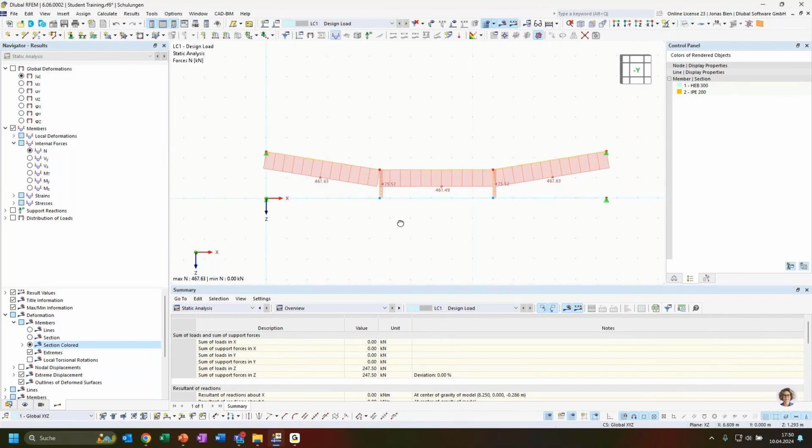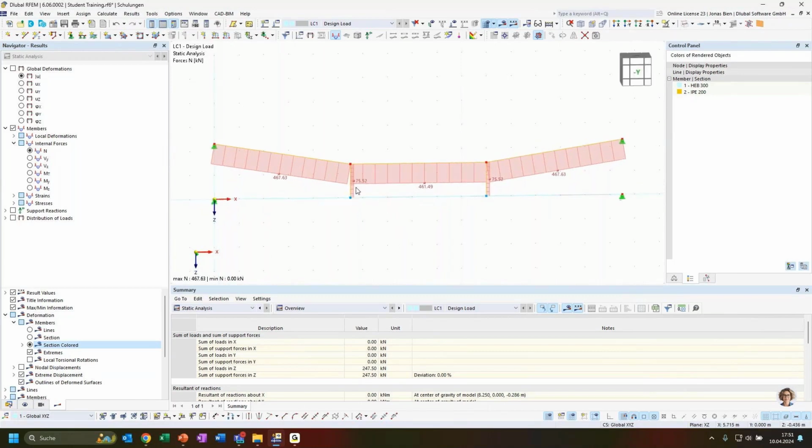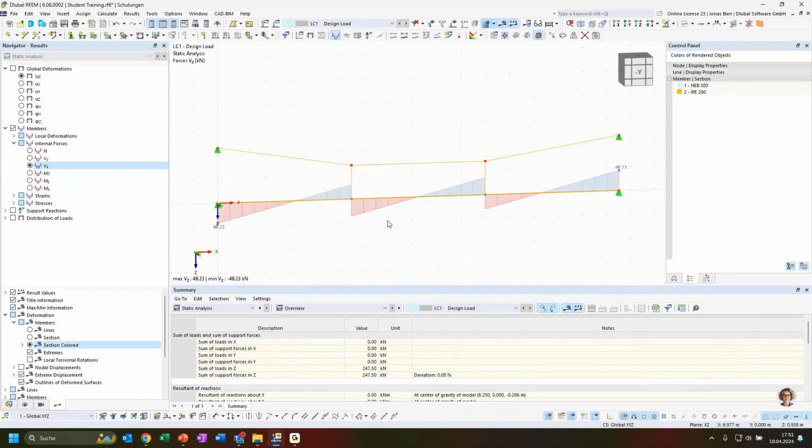I go to the wireframe model and deactivate the rendering, and now I can see that I have very large tensile forces in this above supporting structure, and a vertical normal load in these vertical members of 75 kilonewtons, and these would be the support forces for these intermediate supports of this single span beam. The beam itself is free of axial forces, because I released the horizontal support condition at the member end, but the single span beam below has vertical shear forces and also bending moments around the strong axis.